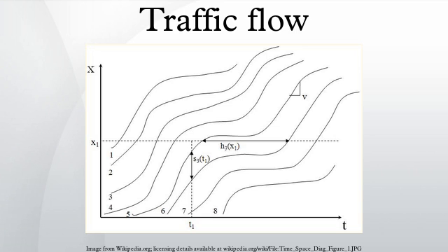over time. There are three main variables to visualize a traffic stream: speed, density, and flow. Speed in traffic flow is defined as the distance covered per unit time. The speed of every vehicle is almost impossible to track on a roadway. Therefore, in practice, average speed is based on the sampling of vehicles over a period of time or area and is calculated and used in formulae.